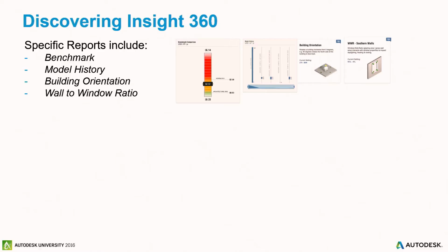What is that going to do? It actually shows you what the current setting is and how it's affected by daylighting and heating and cooling. When you get into window shading, you can say, I want to have this type of window shading included, and it doesn't even have to be modeled. This is just a setting that makes a certain assumption for you that says, I'm going to allow for 2 feet of shade on all my south-facing walls. And I can break it down by different orientations of the building.